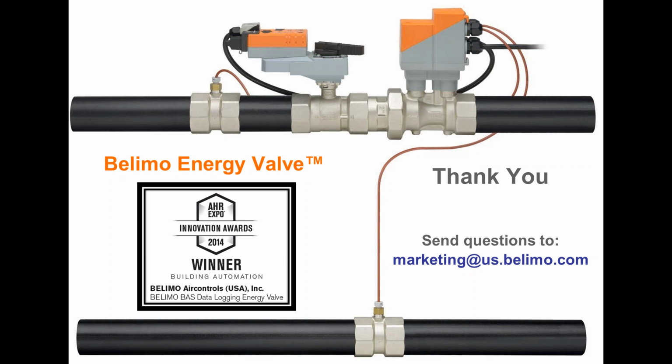The first question we have is from California. How do we get feedback for our California Title 24 to reduce speed on the pumps just to satisfy the worst case load? Gotcha. So California Title 24 requires that the differential, actually, I think it's a static set point in California, but the pressure sensor that drives your VFD has to be reset based on the position of your control valves.